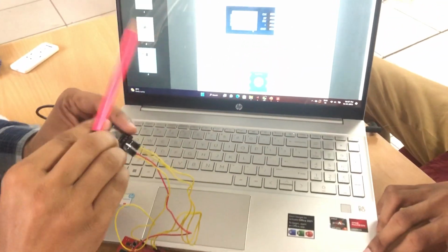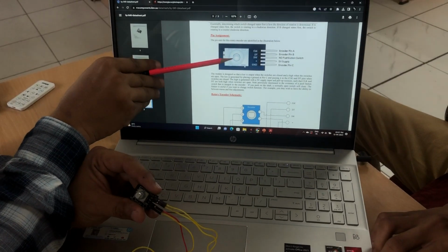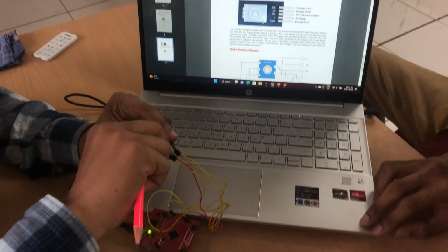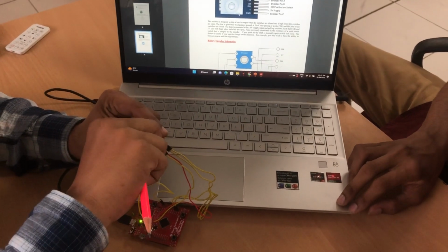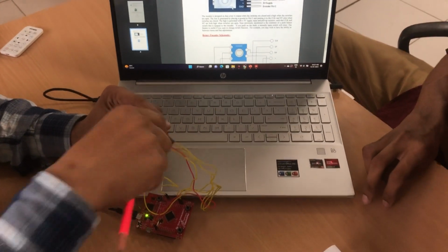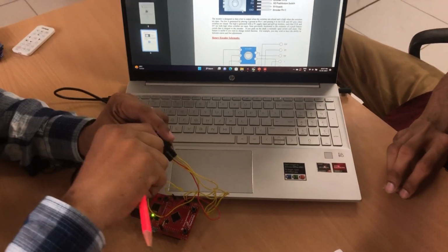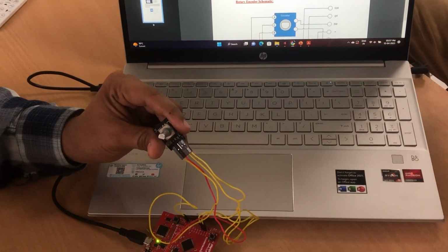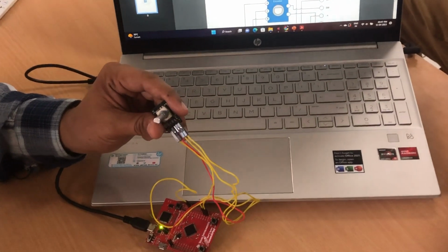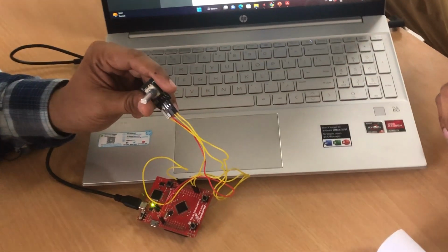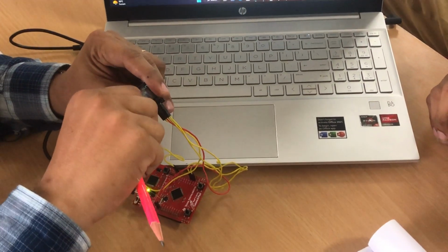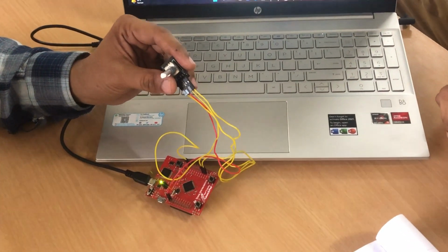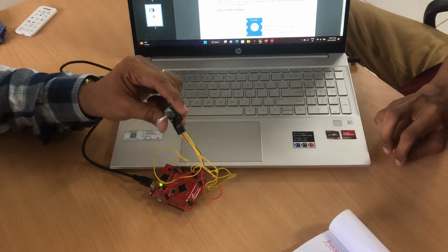So this is the datasheet of the rotary encoder which we are using, the rotary encoder knob. All our washing machines, refrigerators, microwave oven knobs, music system knobs, oscilloscope knobs, function generator knobs are mostly rotary encoder based. Why? Because it replaces the old potentiometer based knob systems. It is more accurate, it is programmable, and the output is only pulses as we see here, and it is very comfortable to integrate with digital systems as we know very well. So that is the idea here.